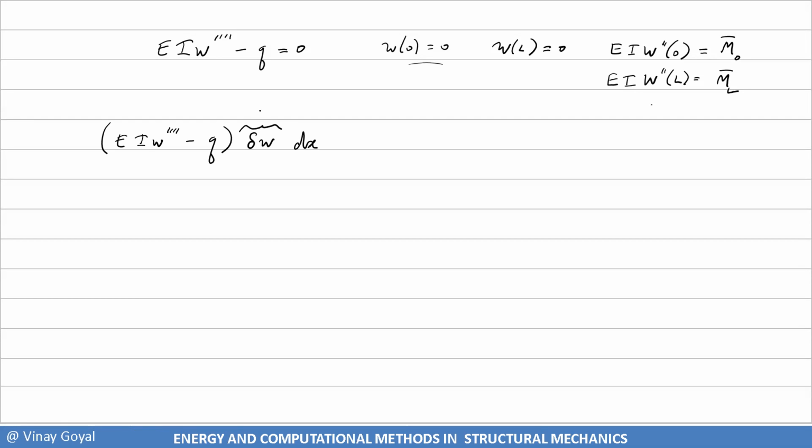And you can also multiply by V, but I selected del W because you can see much easier what's going on, since now you know calculus of variations. So I'll integrate this over the domain, and what I've really done is taken this residual, look at this, taken the residual and plugged it in here and made it orthogonal to virtual variations of the actual solution. Now I'm couching it a little bit differently because I want to bring it closer to what you learned about calculus of variations. We're making the residual function basically adjoint to the space of basis functions or the virtual variations. That's really what we've done there.